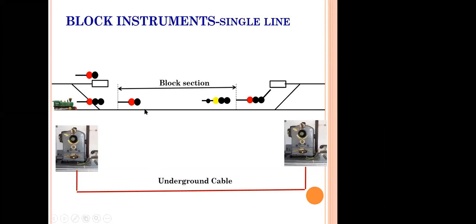One train at a time in this space called the block section, a space interval. The complete area is now blocked for one train. It can be a full train of 700 meters, 70 vehicles, or a single engine of 10 meters. Irrespective of the length of the train, the complete section is now reserved for one train. Hence, it is called a space interval.